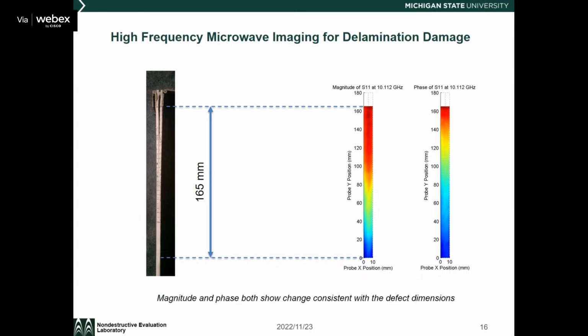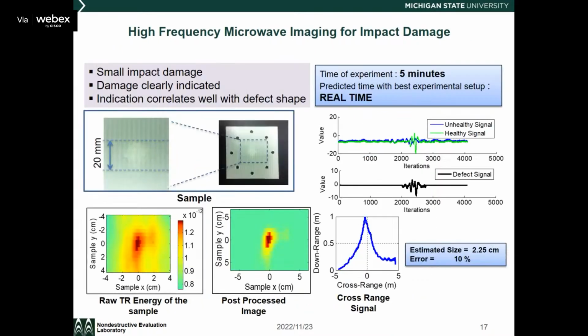Some examples of microimaging for delamination: the same geometry, you can have similar data but different physical meaning, right? Although they have the same color here, the physics is completely different when you look at low frequency capacitive, inductive, or high frequency microwave measurement. Same sample, now instead of using capacitive measurement, you can use microwave. And this is a high standoff implementation. High standoff means that the sensor and the objects are actually far away from each other.